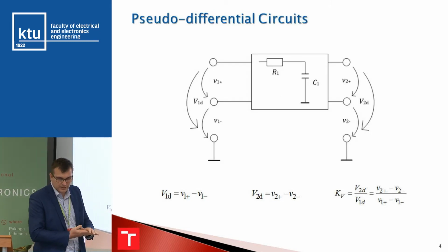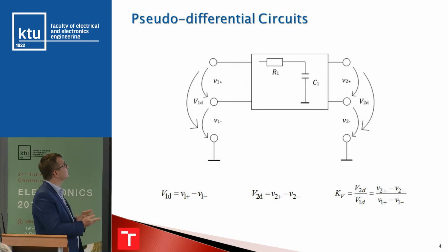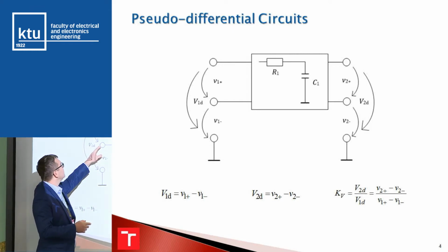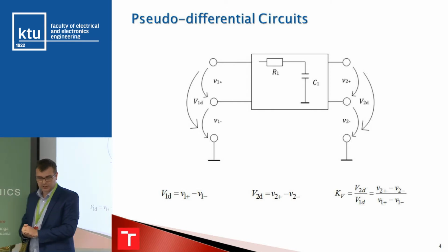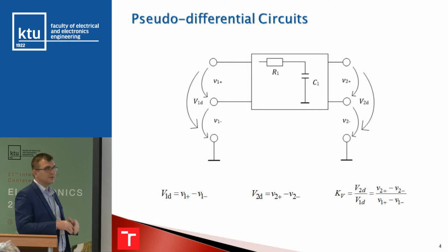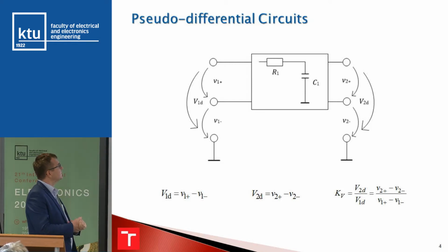But on the other hand, we can also speak about differential circuits in the case where we have the differential input, differential output and the differential voltage transfer, because this is only what the math says about differential circuits, and the inner structure is actually single-ended, resulting in a simpler structure at the end.